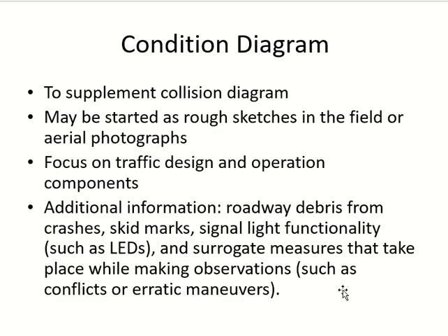Okay, then we have a condition diagram. Condition diagram is a supplement to the collision diagram. Okay, so you read both diagrams together. In the condition diagram, you are showing the condition of the site. This one doesn't have the collisions, it doesn't show the crashes, but it shows more information about the site. So the previous one has less information about the site, more information about the accidents. This one, the other way around.